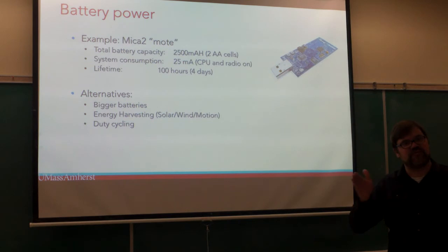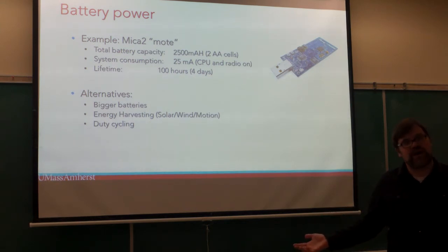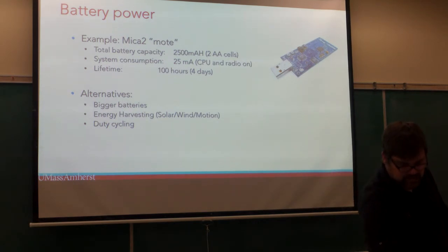Because basically you can send a very long transmit packet, so when the receiver wakes up, you'll hear part of that packet. So you're sort of shifting the burden of power from the receiver to the transmitter, but if you're clever in the ways that you manage this, then overall, throughout the battery-powered network, you can achieve something much less than the 25 milliamps that's listed there.